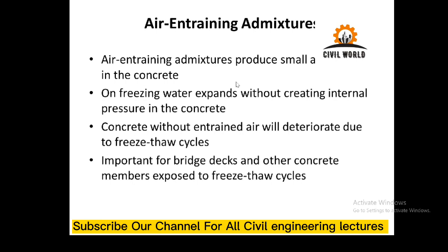So the major impact of air entraining admixture is to avoid the initiation and increase of cracks in the concrete because of freezing and thawing effects. So they are important for bridge decks and other concrete members which are exposed to freezing and thawing cycles in extreme weathers.